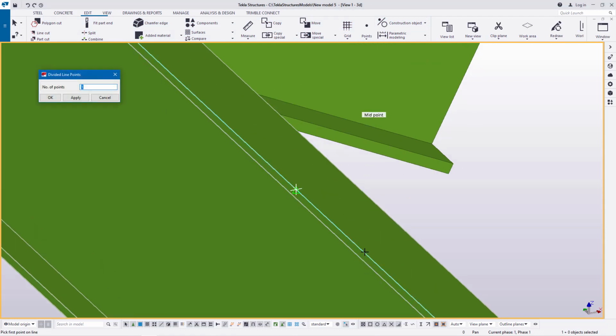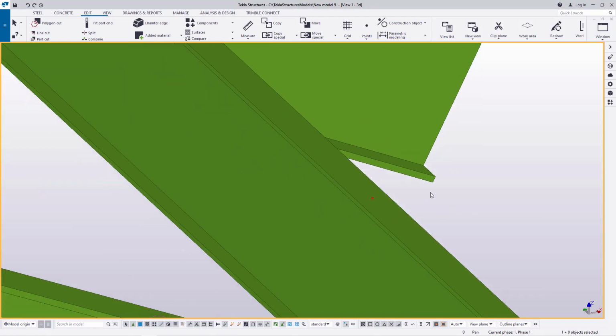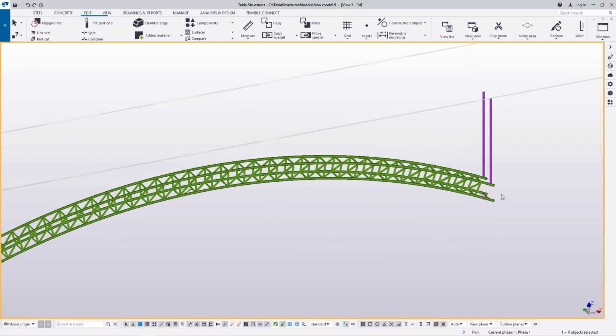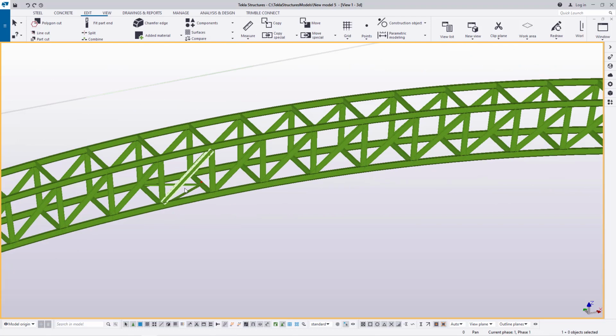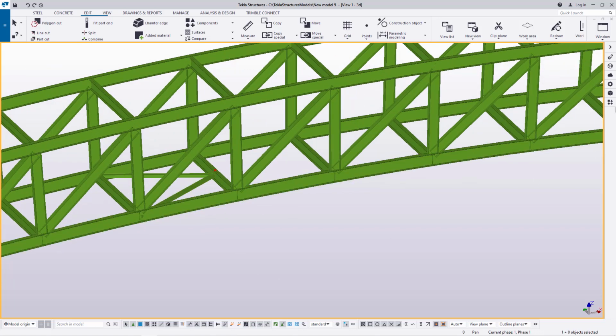The first option you pick when you want to mark the center point of any 2 points. Now I'll snap on this spot and snap on that spot. I'll get the midpoint of that beam. Now I have 3 points here. These 3 points are going to set the exact locations and positions where these bracings will be placed.